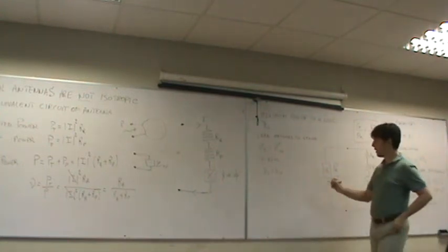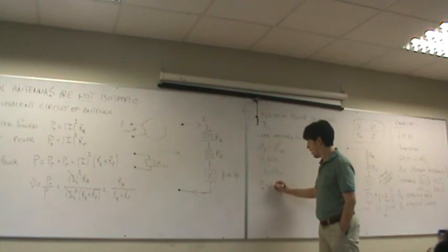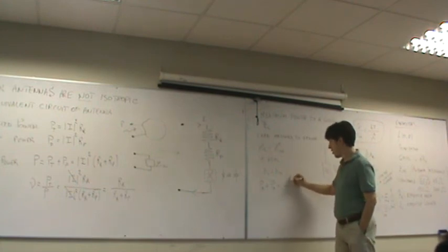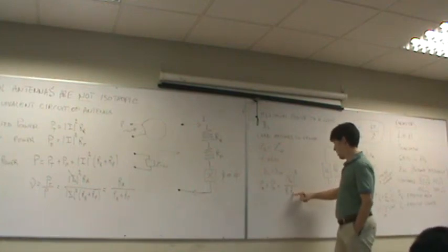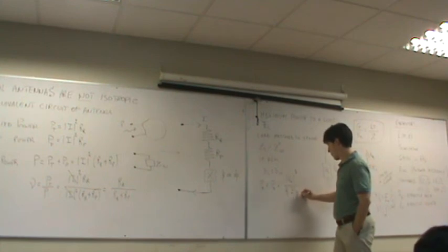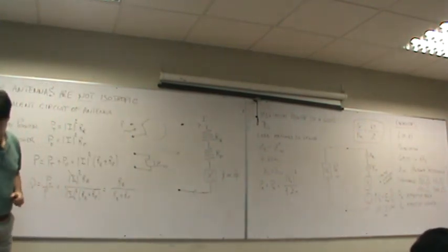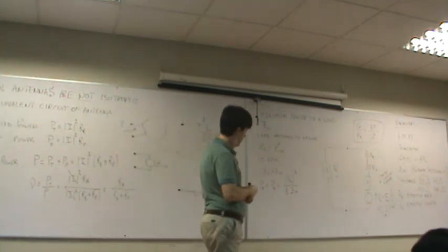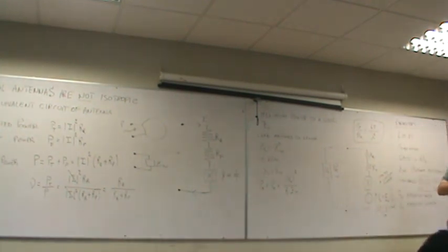What is the value? It can be demonstrated, maybe you know that in this situation, the power to the load is the so-called available power, and is equal to the maximum power that you can transfer to your load.